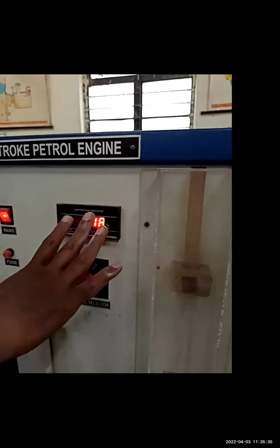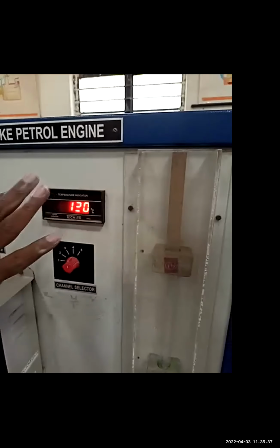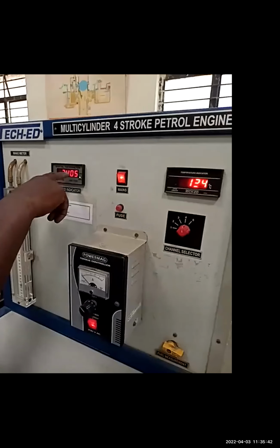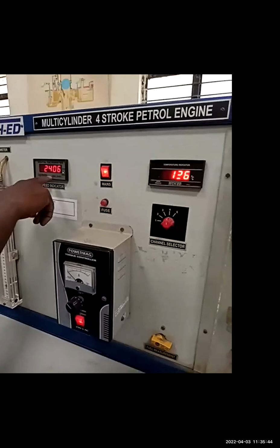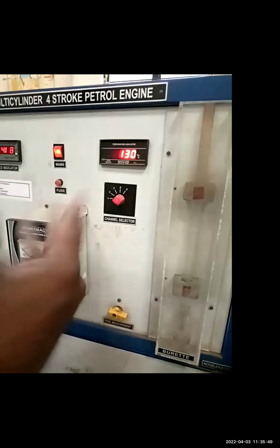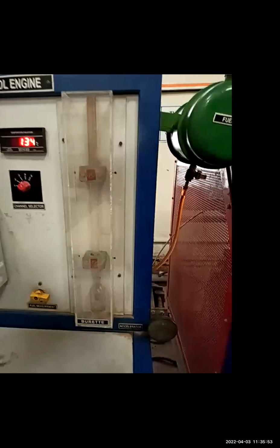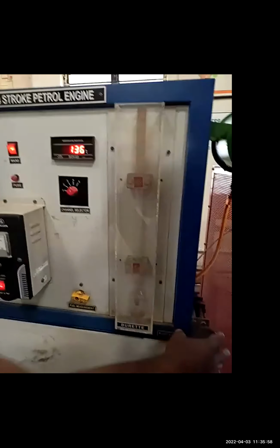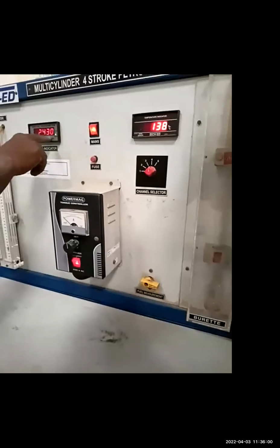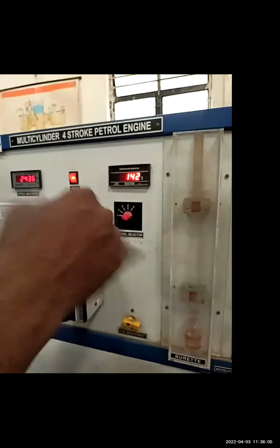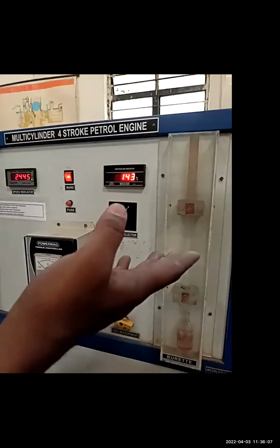Now you don't measure the temperature. It is for another test. Let it be as it is. So presently what you will require is to take the reading of the RPM over here and change the load at different loads, and you find out the torque. Every time ensure that the speed remains constant. Whenever you change the load, using this, ensure that the speed remains constant. For the same speed, you have to measure all the powers.